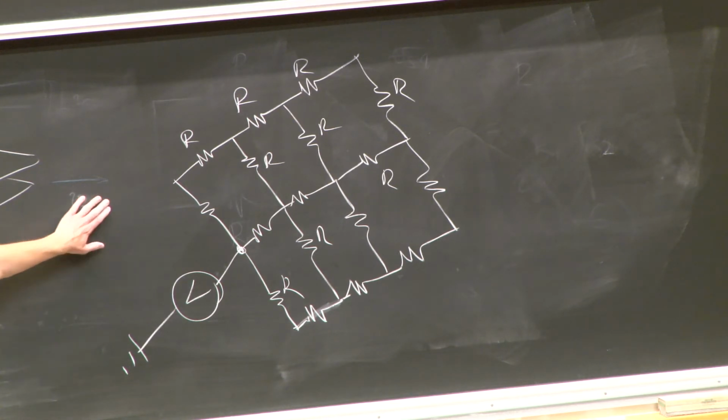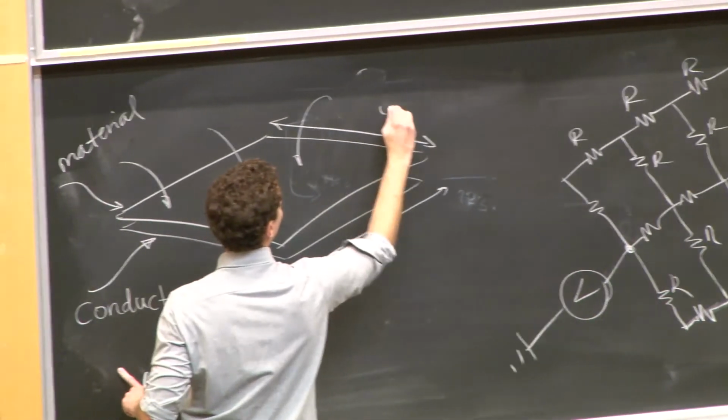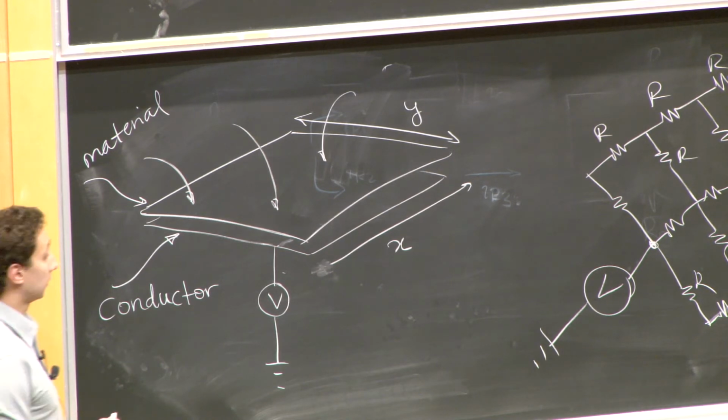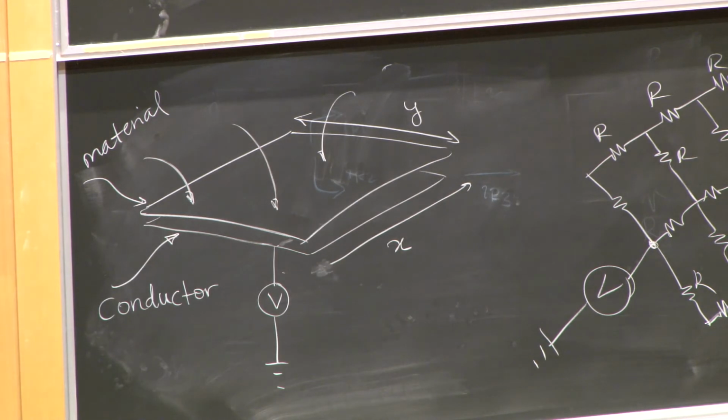So the suggestion was, what if I, along each line, measure the voltage, and then measure the voltage along each column, and sort of triangulate, not exactly triangulate, but extrapolate where the touch is. So basically do an x dimension measurement. Let's say this is the x dimension, and this is the y dimension. And basically do the same thing that I did for the one-dimensional touchscreen, but twice, right? So once to determine my x-coordinate, once to determine my y-coordinate. It's an excellent suggestion.